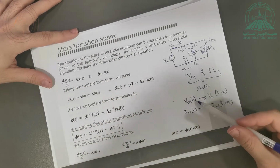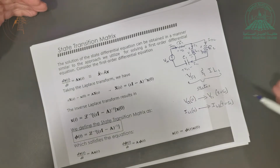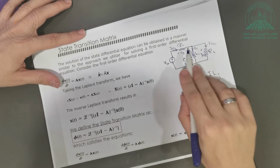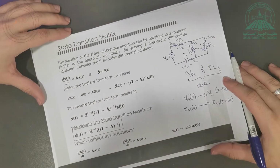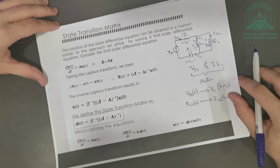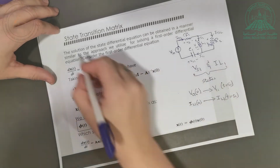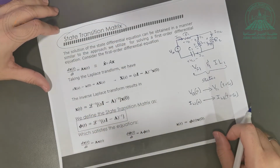And if I know VC1 and IL1 at any point in time, I can find everything else using the regular circuit laws and equations that I'm familiar with: KVL, KCL, Ohm's law, and so on. So our task now is to learn how to get this state transition matrix, which is very, very important.